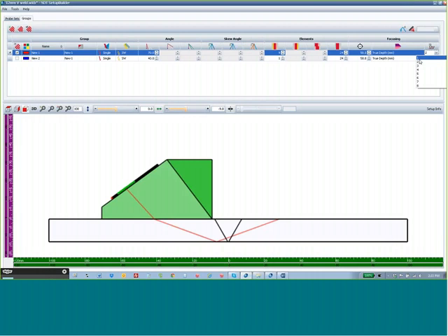So the high angle, 70 or 72 degrees, we want exiting as close to the weld as possible without interference from this wedge dampening. Some of the Olympus probes and wedges allow a 16 aperture beam to interfere with the dampening here, and it's dependent on the operator to move it back a couple elements. This happens on the A12 and the A11 probes and wedges. So the new weld series was given a little bit more consideration regarding this.